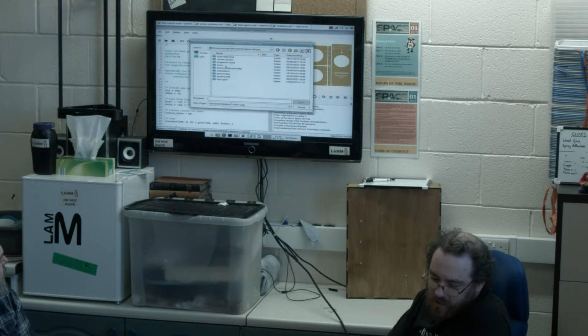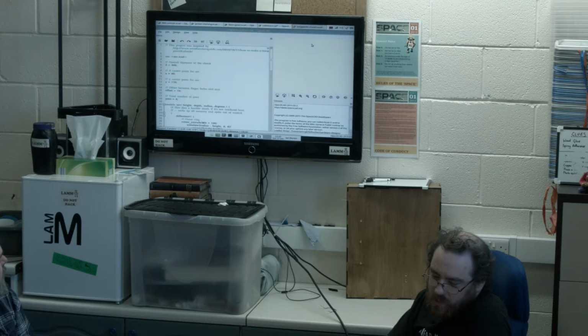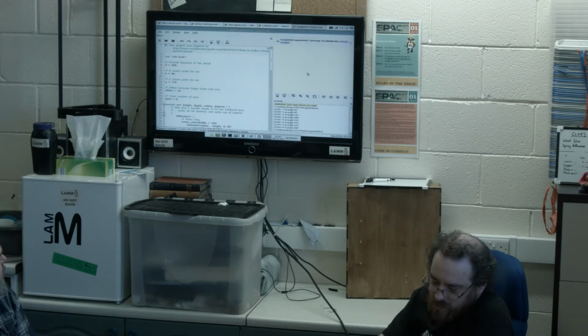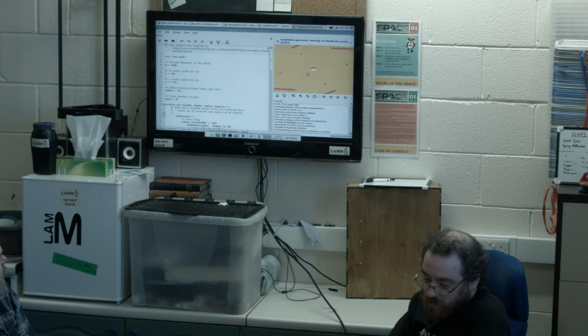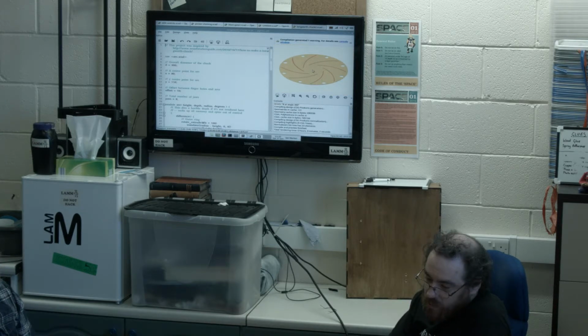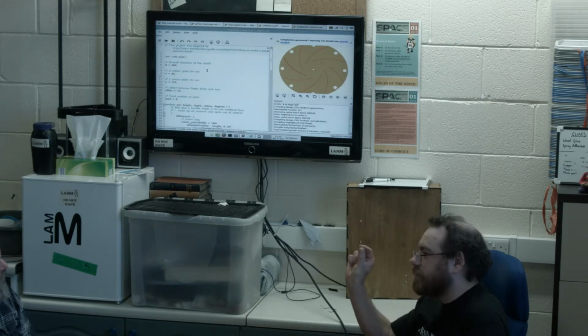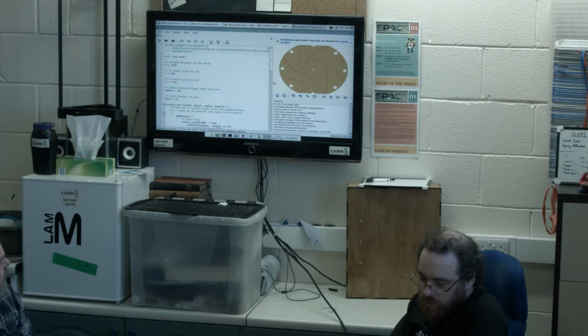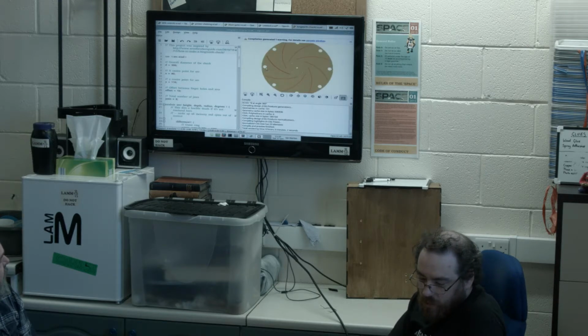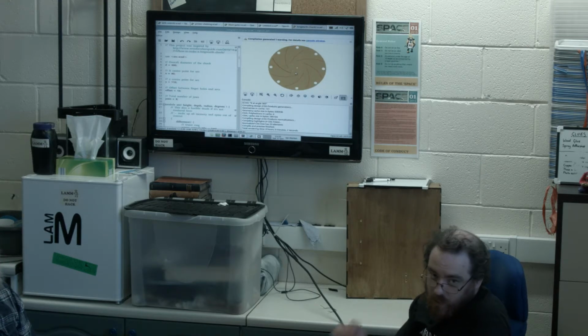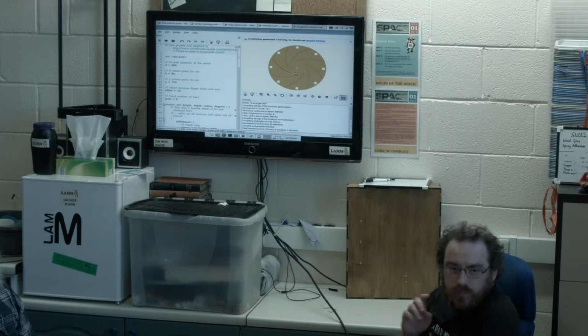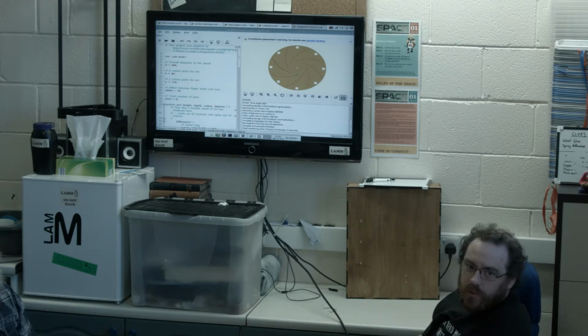No, because I messed up the implementation. The maths on it is kind of horrendous. No, it wasn't the maths in the actual system. It was when he cut it on the laser, he forgot to unite the circles, so you ended up with lots of little bits of lines. Yes, that's one thing with OpenSCAD: when you export circles, they end up as lots and lots of lines.